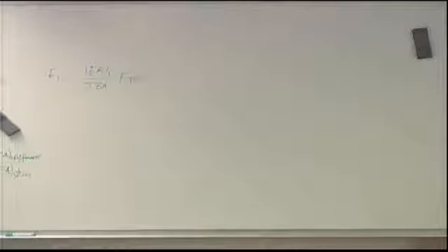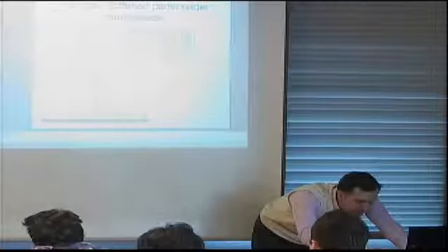The force in member i is just the EA divided by the sum of the EAs. So the last column, therefore, is just the ratios of the EAs divided by the sum of the EAs.